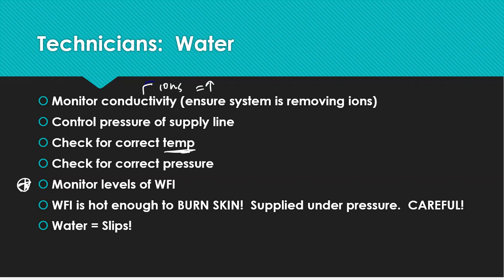Next up, water for injection, we said pressure and heat, right? We constantly circulate, we constantly heat. So because we are heating things like water, you want to be really careful when you are exposed to it, or when you work around it. So make sure that you do not burn yourself, please, or get hit with constant hot pressure. The last thing that we want is to be scalded by the pressure, or by hot piping, or hot vats, or hot valves, or hot pumps, and so on. So use some common sense. Make sure that you work very carefully around it. I know it's water, but water is not the problem here. It's the temperature and the pressure that it's bringing to the party with it.